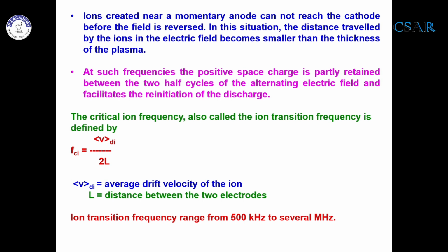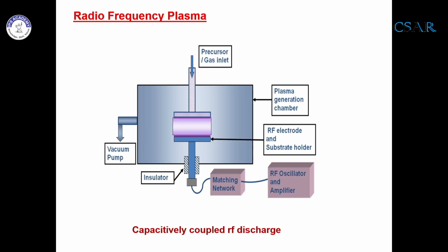However, you are at an advantageous situation because the impedance of the dielectric falls at high frequency. Now, if the impedance of the dielectric falls at high frequency, then you are better off because the RF energy will interact through the RF field, because this dielectric, whatever is put onto this cathode for sputtering application, has lost its impedance, it is reduced. So the RF field is able to permeate through this dielectric, and its effect can be felt by the plasma constituents.